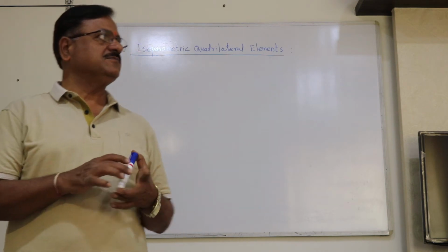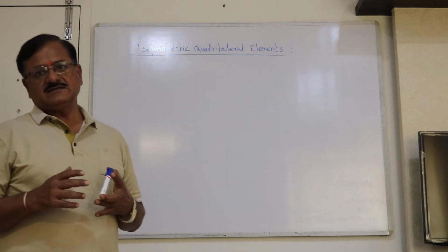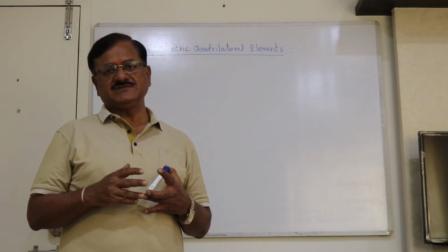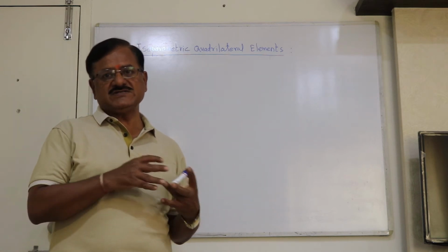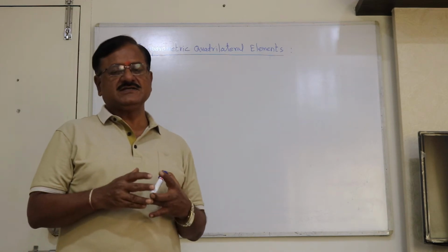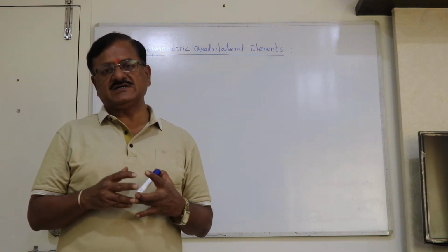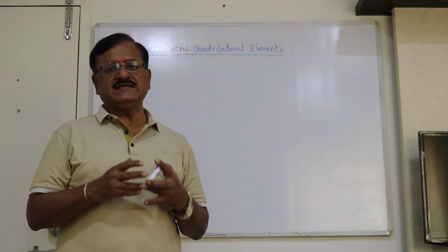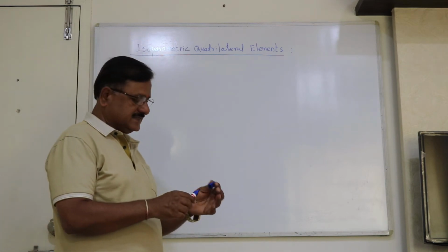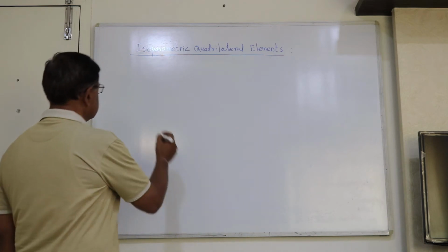The quadrilateral element always has 4 sides, and since we are using the natural coordinate system, the values always vary from -1 to +1. Hence, whatever the shape of the quadrilateral element, mathematically the element is always a square element.